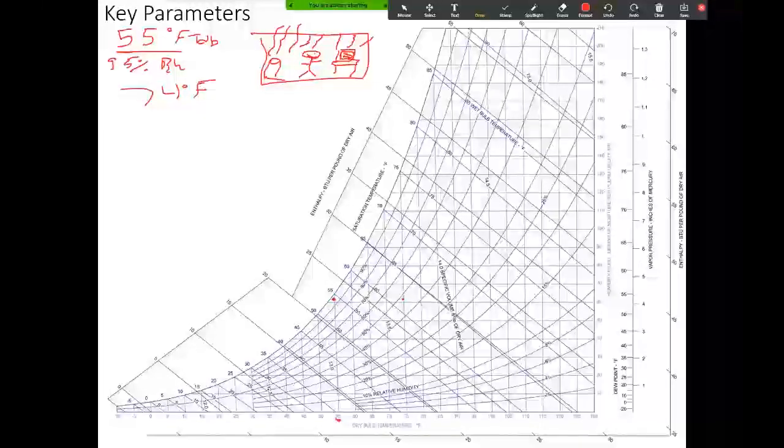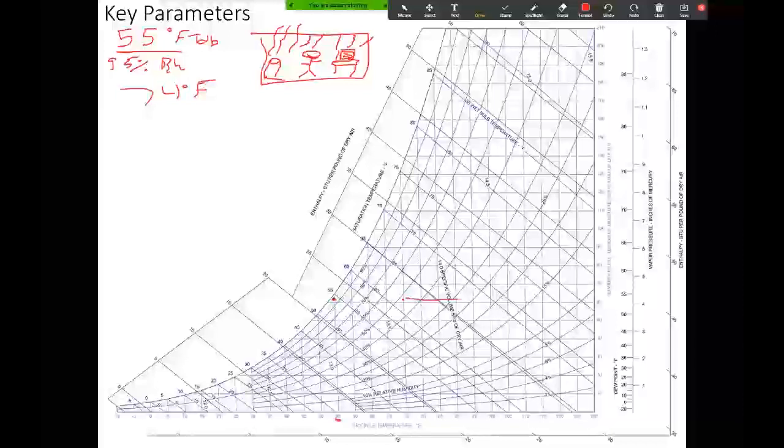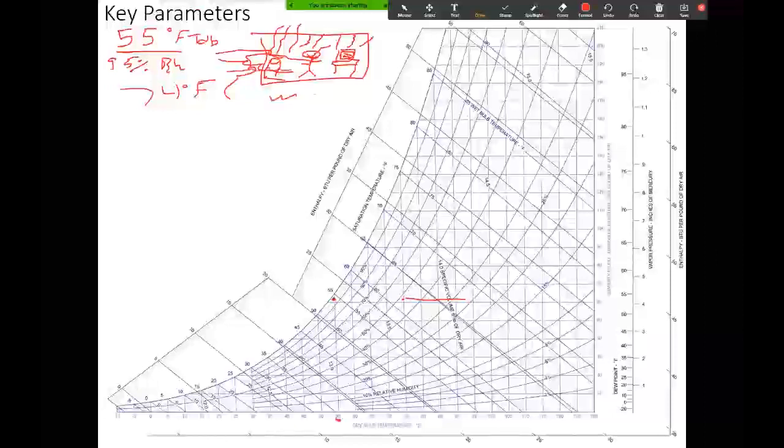and then it's going to continue to increase. So the temperature is going to go up even more. And when you're in a restaurant or even at school, people are sources of pollutants, right? So when I breathe out, I expel moisture in my breath. I sweat, I perspire, doors are opening and closing. It's humid outside. I'm getting moisture coming in. I don't know how to draw moisture. I'm getting moisture in from this guy, and if I'm in the cafeteria, from cooking, from boiling water. I'm getting vapor into the air, humidity from the outside. People are sweating, and the humidity is going to increase. So I'm going to increase in my absolute humidity.